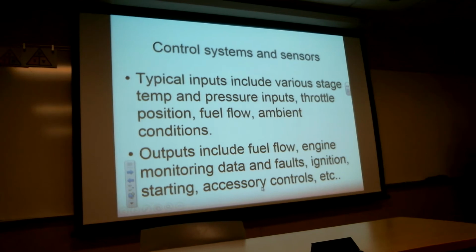We're also going to measure the fuel flow and the ambient conditions, temperatures, pressures, and so forth. All these sensors. So there's going to be several bundles on a big engine. There's going to be several bundles of wire as big as your wrist that will feed inputs and outputs into the FADEC. So that's the inputs. And of course, everything is an acronym, or it has a contraction to it. So I think I have a few of these here. I'll show you what they are.